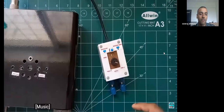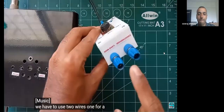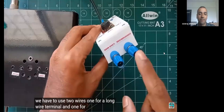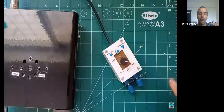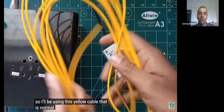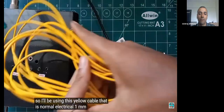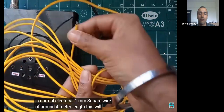We have to use two wires, one for the long wire terminal and one for the counterpoise. So I'll be using this yellow cable, that is normal electrical 1 mm square wire of around 4 meter length. This will be acting as a counterpoise wire.